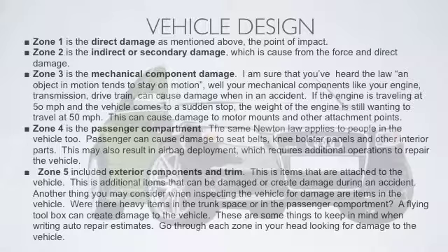It can be a number of things. It can be buckling in other panels from the damage from the force. It could be busted spot welds that you can find in additional panels. Seam sealer that is cracked. I mean, it's not necessarily real easy to see. Indirect damage or secondary damage, you've got to really look for that sometimes, and it can travel throughout the car, because remember, the front and rear absorb, and it transfers around the passenger compartment. So the damage can really travel pretty far on unibody cars.